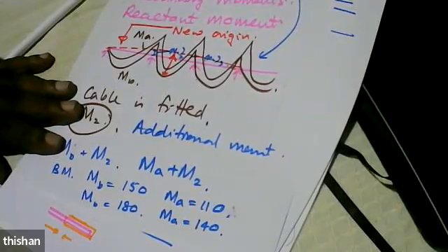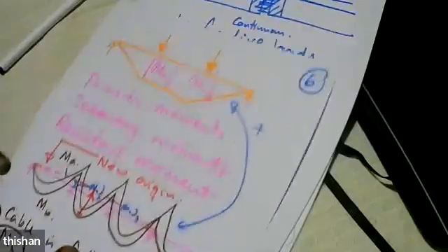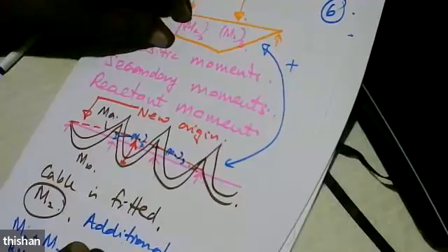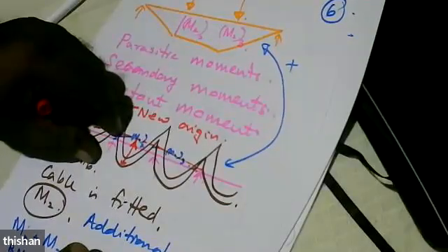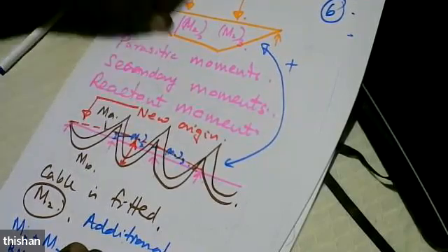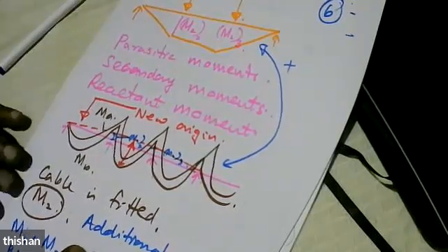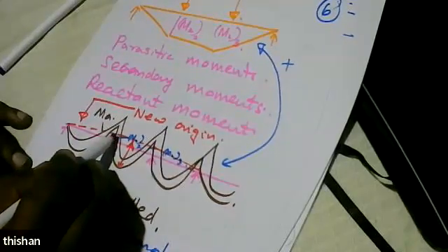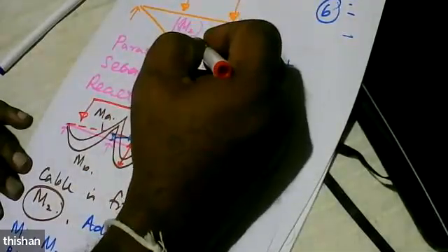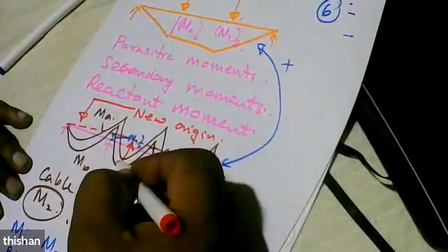So that's how the bending moments increase. Whenever we have two bending moment diagrams that we want to add, we can use the principle of superposition. If this is a sagging moment diagram, this hogging, this sagging and hogging both, this sagging only, then because it's varying linearly, we can mark M2 as a hogging moment, because we know when you add this to this, the moment should increase.